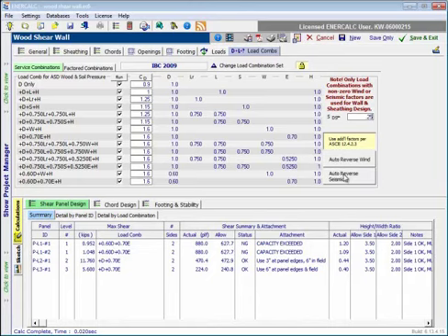Notice also that we have the familiar buttons to indicate that we want to automatically reverse the effects of wind loads and seismic loads. You can choose those, but please choose them wisely, because sometimes the wind loads and seismic loads that you assign are safe to assume can be reversed by an algebraic negative, and sometimes they cannot safely be reversed in that way. So the function of these buttons is simply to create both the positive and the negative forms of all load combinations that include wind and/or seismic. So use those as you see fit.